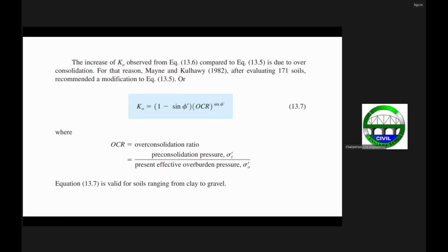When you have a dense material, that means you have an over consolidated material. When you have stiff or hard material, that's usually an over consolidated material, for example. When you have soft to medium stiff, I guess, you have a normally consolidated material.